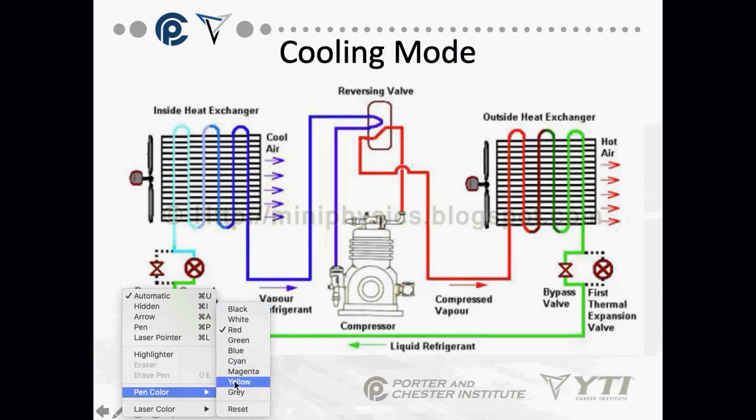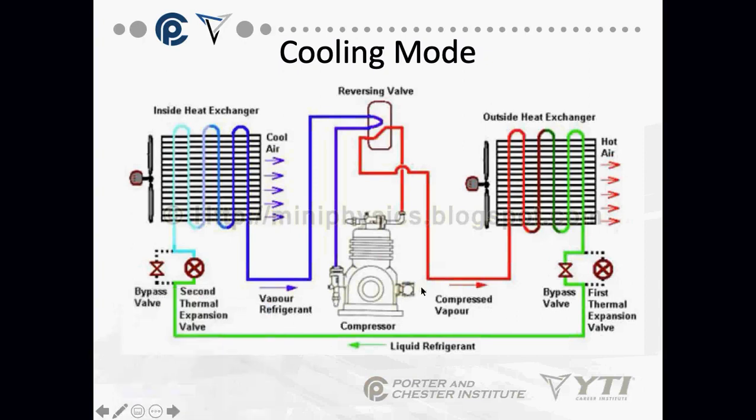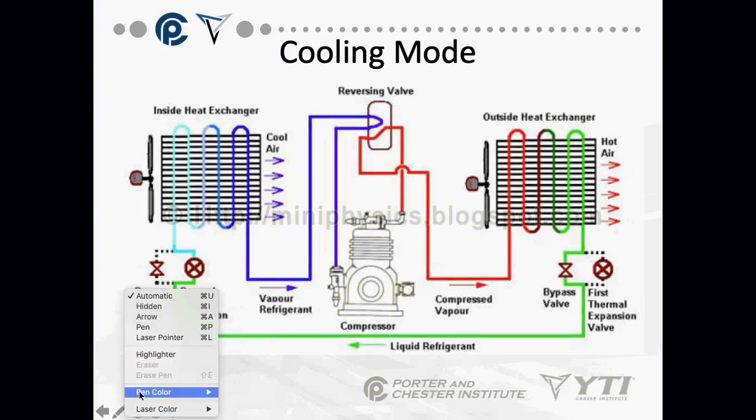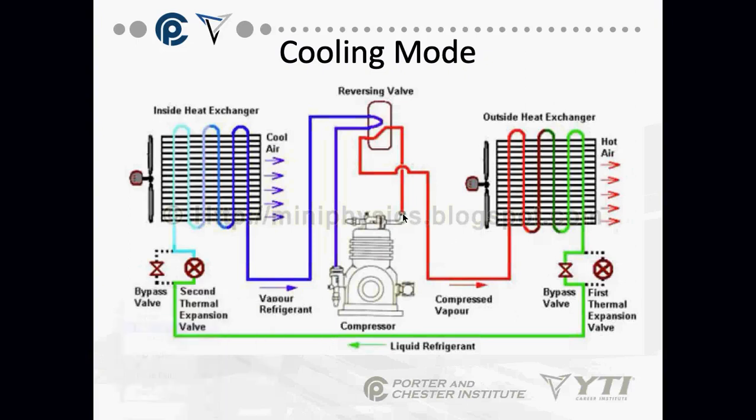I'm coming out of the compressor, and I'm coming through the reversing valve with my discharge gas. I'm coming to the outdoor coil where I'm doing my normal thing a condenser does: de-superheat, condense, and subcool. I come out of the coil, but I don't go through the TXV that's on that outdoor coil. I bypass it through a check valve.